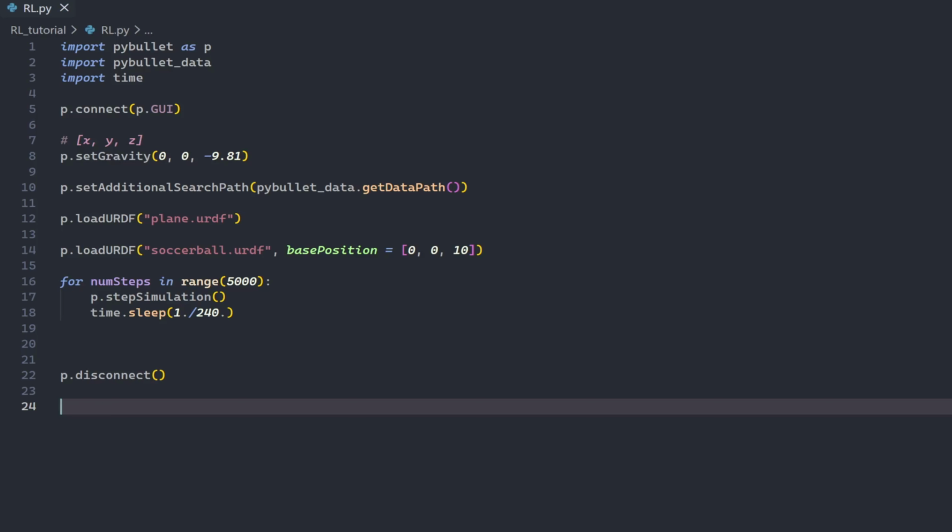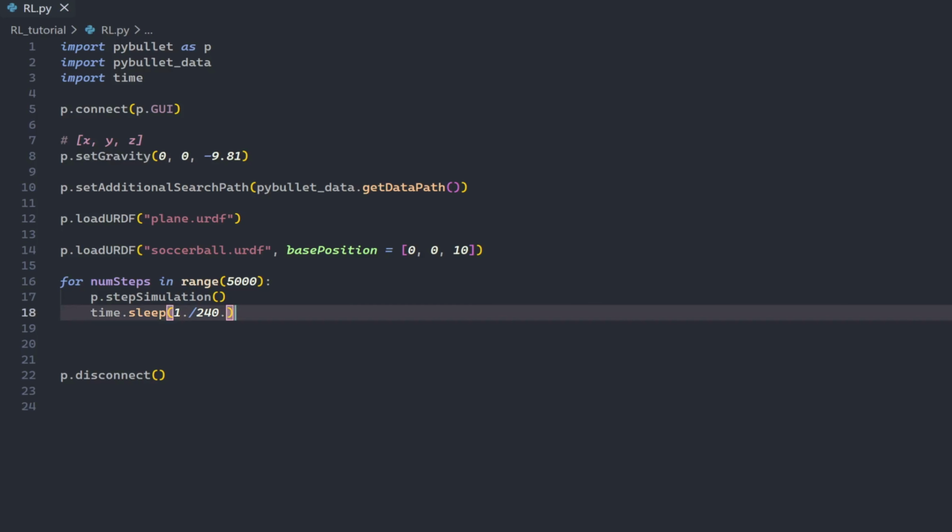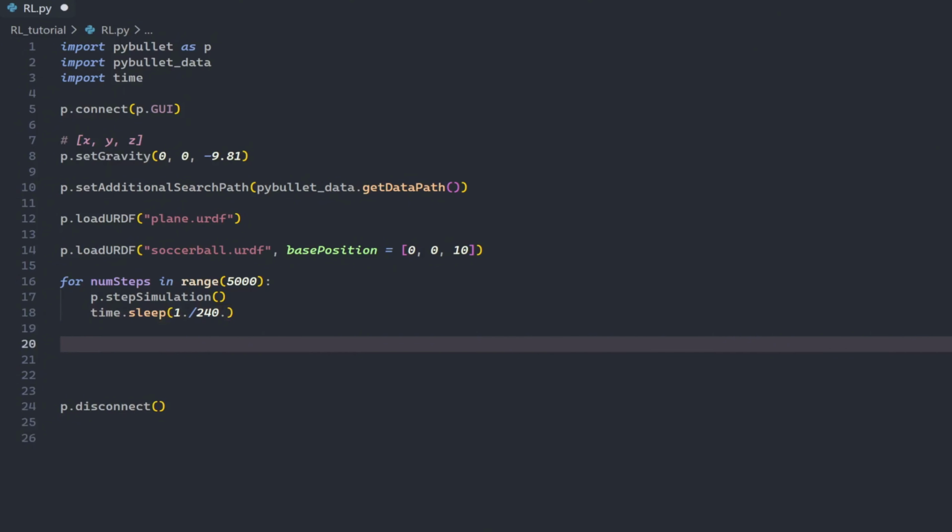Let's begin with getting the object's coordinates in real time. How can we do that? To achieve that, we can use PyBullet's function called getBasePositionAndOrientation. This will output both position and orientation. In other words, we will get x, y, z, and w. Orientation represents a full rotation in three-dimensional space, not a 2D angle, and PyBullet uses normalized quaternions to avoid gimbal lock. We will just throw away orientation first and focus on position, which is simply x, y, and z.